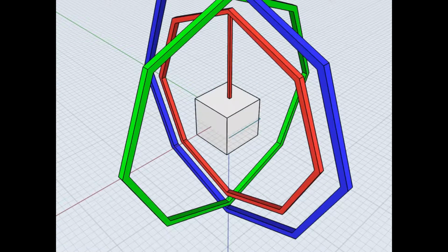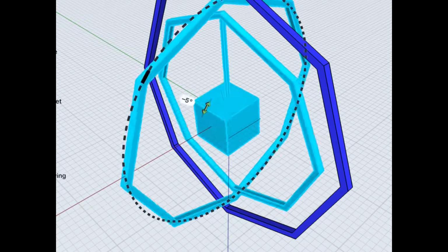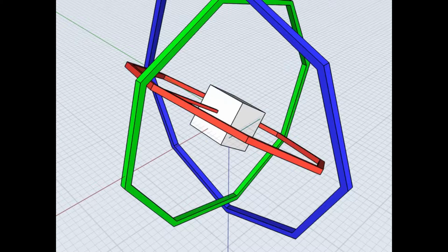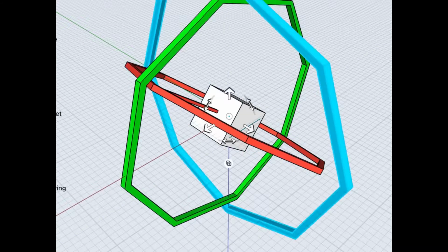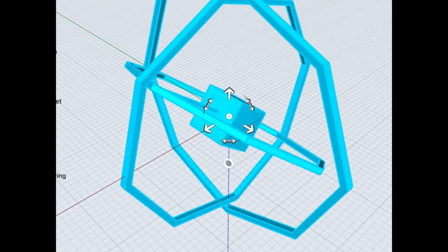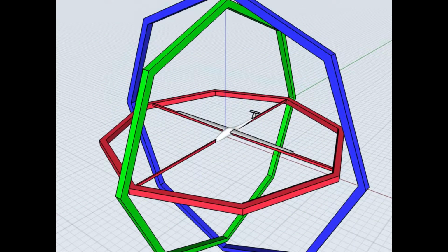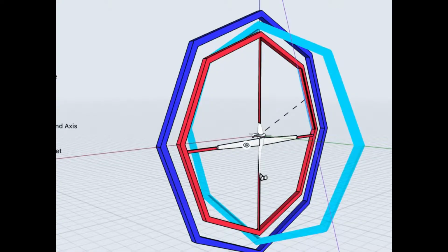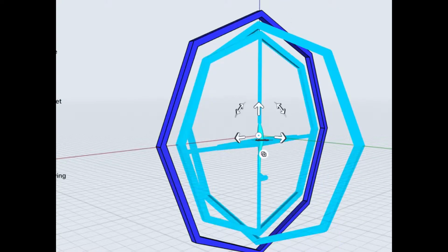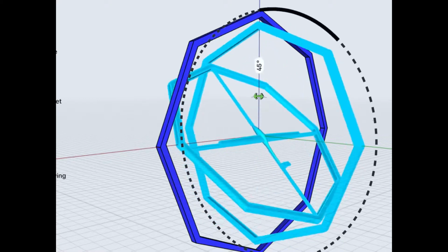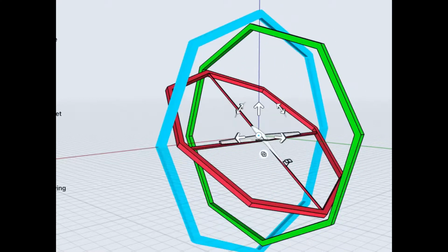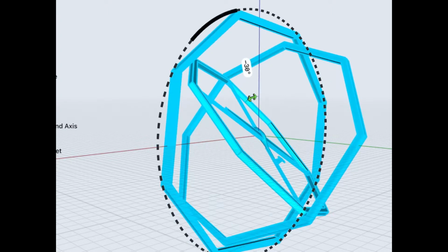This is what is known as gimbal lock. Nothing is physically constrained or locked, but a combination of controls must now be implemented in order to separate the aligned axes and enact a roll maneuver. For example, with this diagram of an aircraft, in order to cause a roll of the aircraft, the y-axis would now have to be pitched down and rotated.